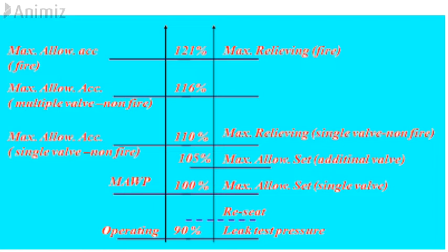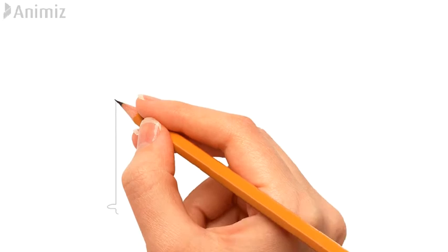Basically, I want to say that the concept of 110%, 116% and 121% of MAWP comes from old pressure relief valve design, which requires 10% overpressure above the set pressure of the PRV. Otherwise, we may face repeated opening and closing, leading to the PSV chattering.